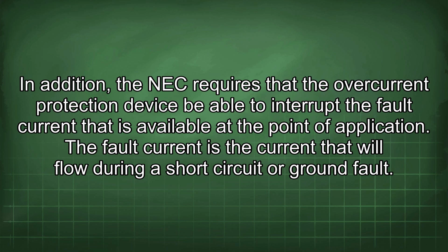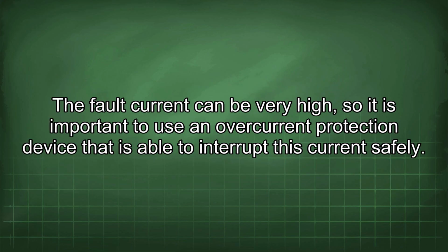The fault current is the current that will flow during a short circuit or ground fault. The fault current can be very high, so it is important to use an overcurrent protection device that is able to interrupt this current safely.